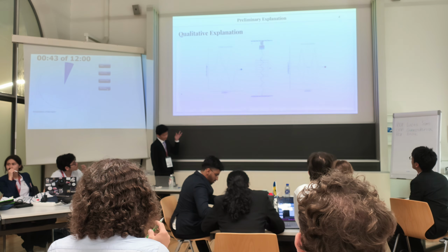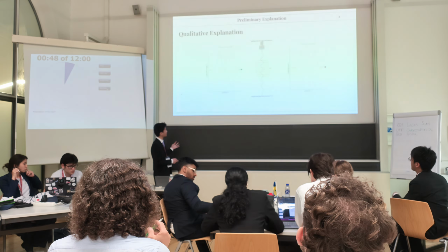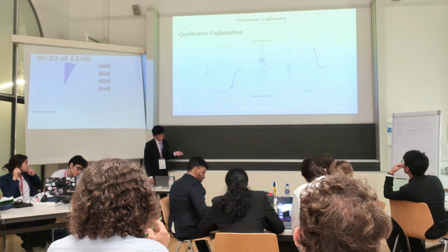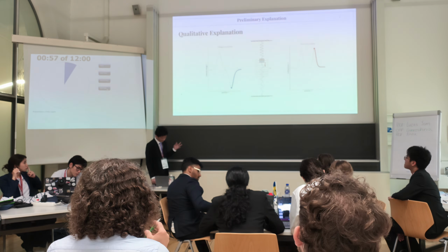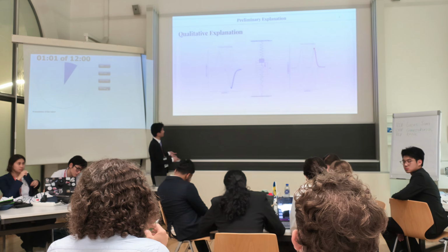At the very top, the magnet is momentarily at rest, so there's no flux change to the coil, and so there's no voltage, no braking force. However, as the magnet starts to fall, it picks up some speed, and somewhere between the peak and the rest position, the flux through the coil will change fastest, and so this is where the induced voltage and braking force will reach the maximum.